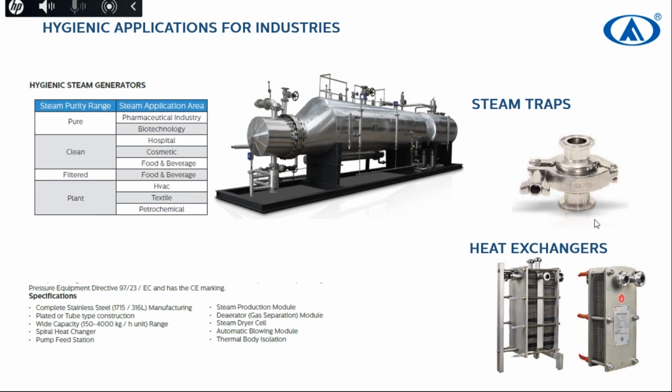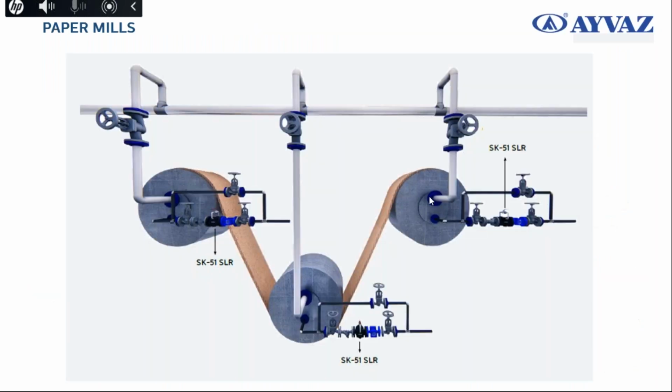You can use this thermostatic stainless steel steam trap, or our SK61 types of steam traps. It's fully stainless steel, or the TKK42 steam trap, thermostatic for air releaser, right here. And you can use SK61, as you see here, with stainless steel body and all particles inside.